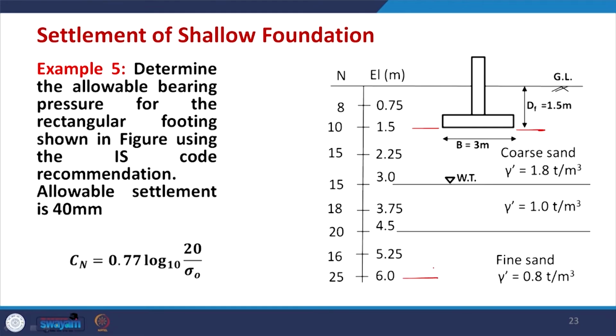So, what we do simply, the concept is, you apply the required corrections, the two corrections we already discussed in the last lecture. One was the correction due to overburden pressure, another was due to dilatancy. Applying both corrections you get the N values, and these N values should be at an interval of 0.75 meter, that is the suggestion. And if the strata is changing, then you need to again get the N values.